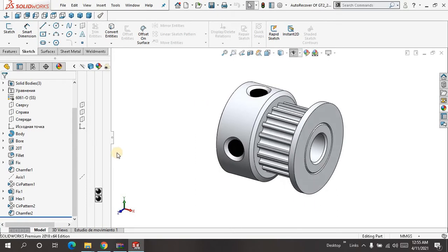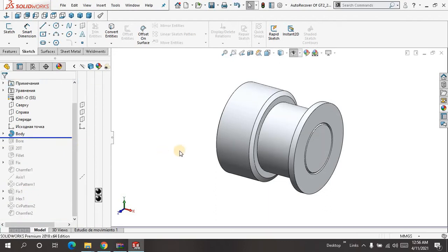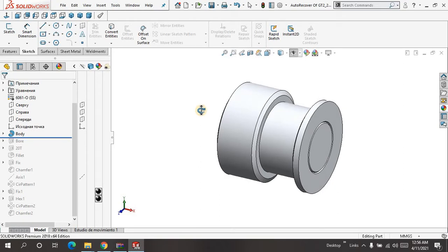Okay. So let's first superimpose the files that we have applied in making this timing pulley. So let's just come here, and when it's converted into paint, you just have to click here on the green line and drag it upward. Let me superimpose the other features, and let's have a look at the first sketch from where we began to model this part.